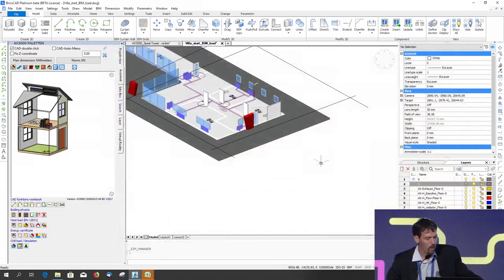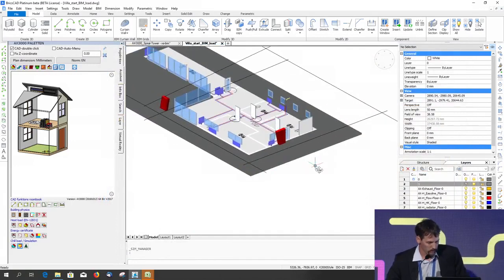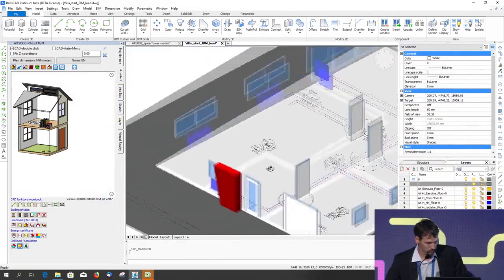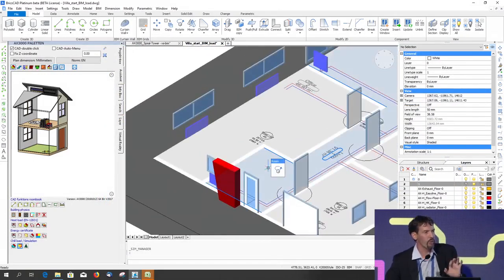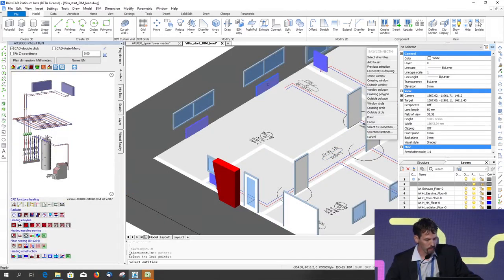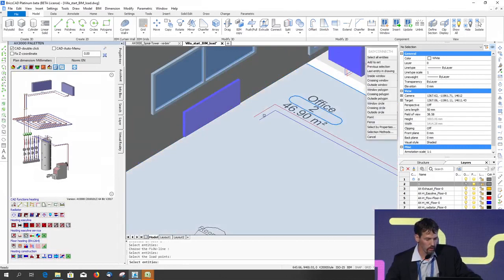At the end of the calculation, you get radiators. You can see here. And now we're at the same position that we started the ventilation module. They are placed by the software under the window. You can do it, you can manage, you can manipulate. You connect the radiators to the line. So I select my 2 radiators. I say this is the flow, this is the return.